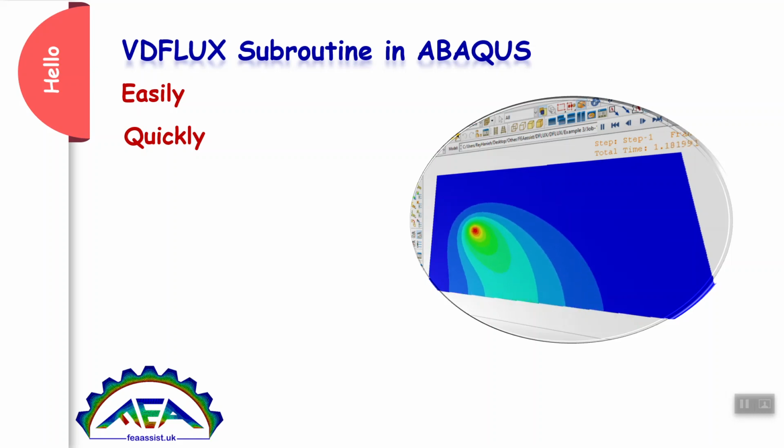This VDFlux subroutine is solved by a temperature-displacement explicit solver in Abaqus. DFlux is solved in a standard solver, while VDFlux is solved by the explicit solver. To understand how it works, stay with us.